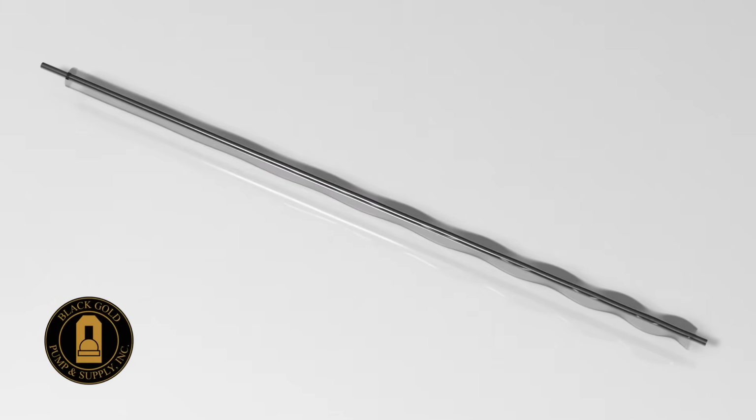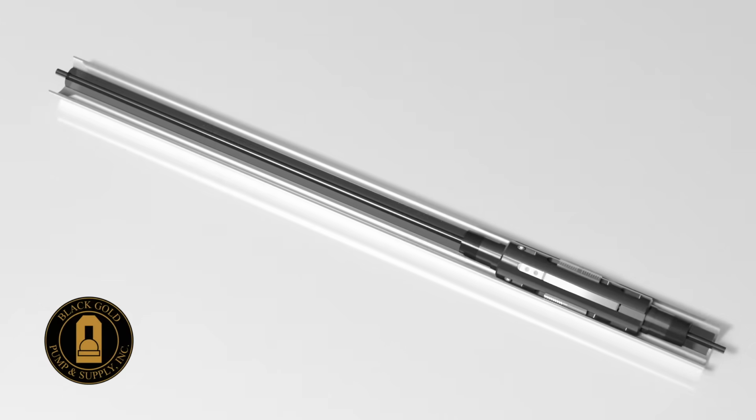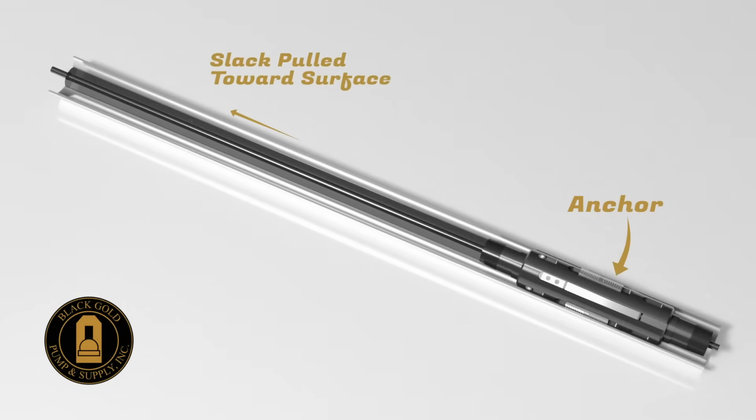During the downstroke, the load is held by the pump standing valve at the bottom of the tubing string. As the unit lifts on the upstroke, the load is transferred to the plunger traveling valve and the rod string. This alternating load causes the tubing to stretch during the downstroke and contract during the upstroke. Lubinsky gave us a way to mitigate these negative effects by anchoring the tubing near the bottom of the well to keep the pump and tubing string stationary.